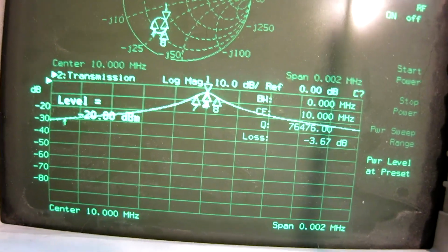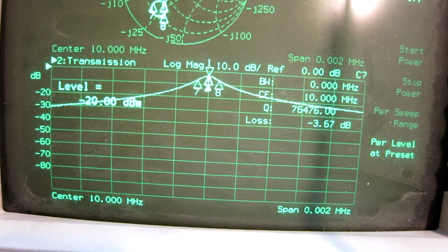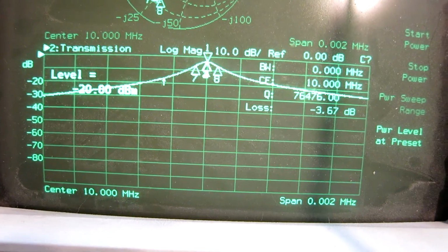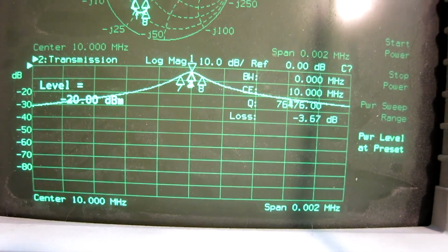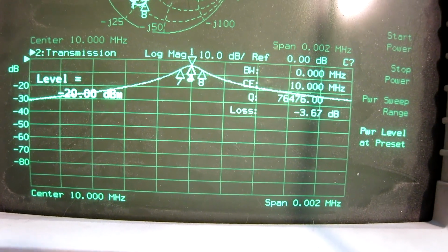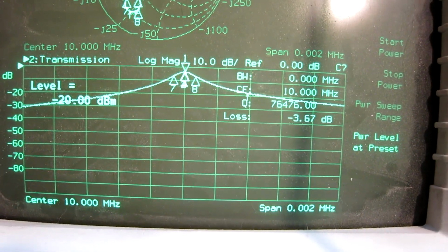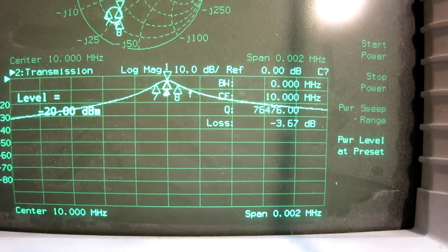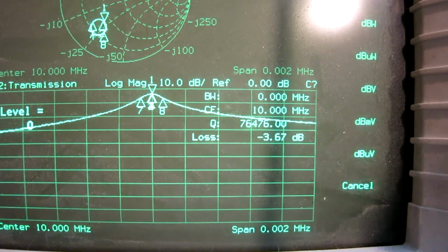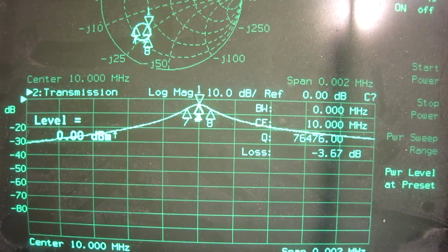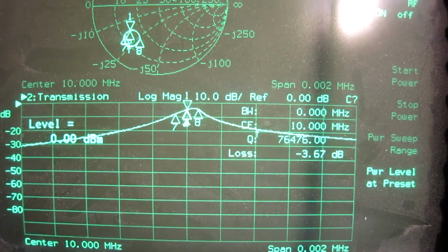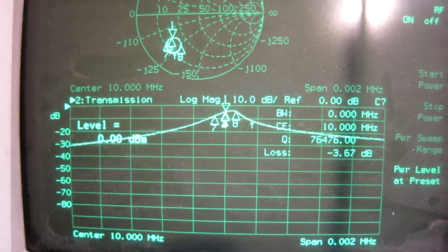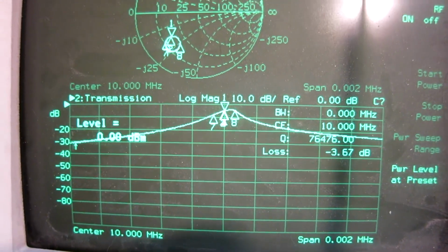I have added an amplifier and an attenuator to set the level 6 decibels higher. It means the loss reads now 3.5 dB approximately, while it was 9.5 before. And this is at minus 20 dBm, and I go for 0 dBm now. And if you look at this curve here, the change is very similar to what I had with 1 crystal and 6 decibels lower power level.